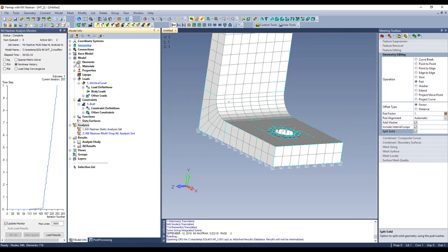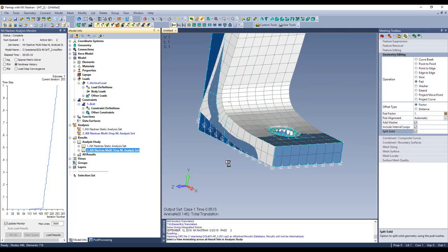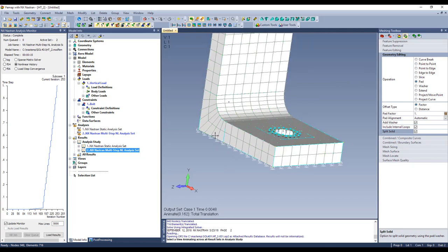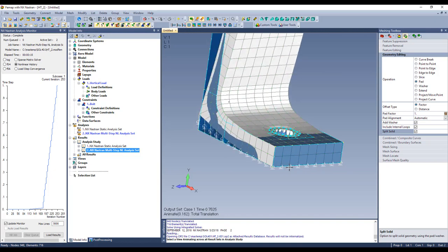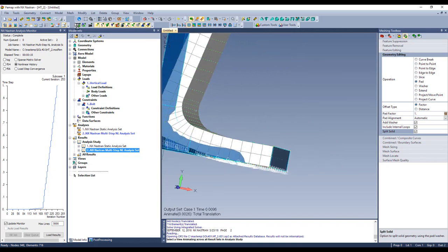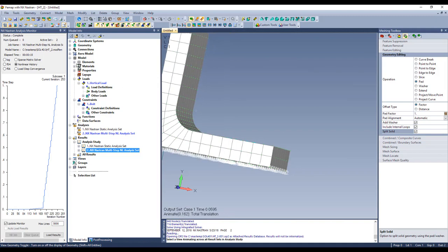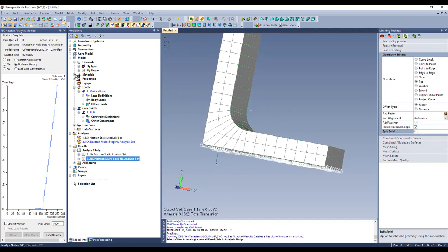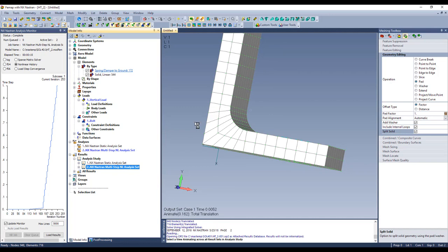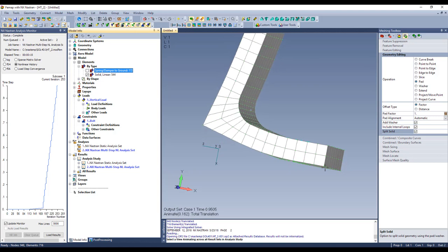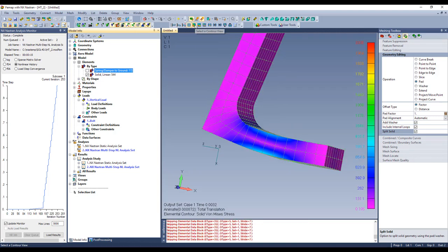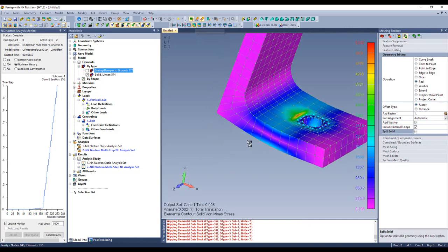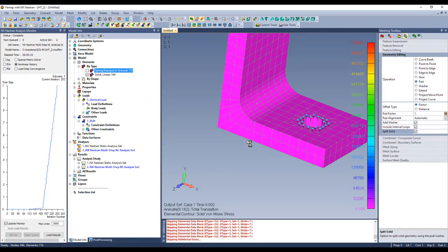So let's go look at those results. So now we got, those are all the results. Let's go look at just that multi-step, and I'm going to say animate this study. And you'll see I had that first small time step to allow stuff to get kind of connected and going. What you can now see, I'm going to turn off my geometry. And let's turn off all those one-way elements. So elements by type. Well, you'll see that it never goes below 0 here. So we're kind of getting that heel and toe effect. And just for fun, let's turn on the stresses. Yeah, looks good.